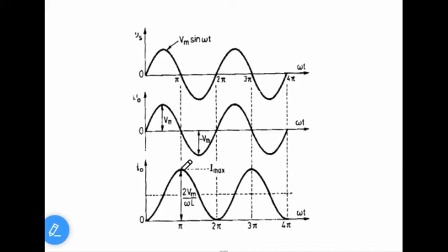Therefore, the switch cannot turn off. If the switch turns off, the entire energy appears as a spark across the switch. Therefore, even though the supply voltage enters negative, still energy is there in the inductor. The current cannot go to negative, or the SCR cannot stop conducting here. Therefore, you will get one positive pulse for one cycle.